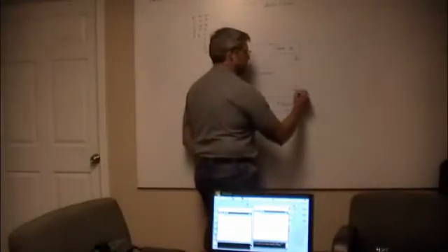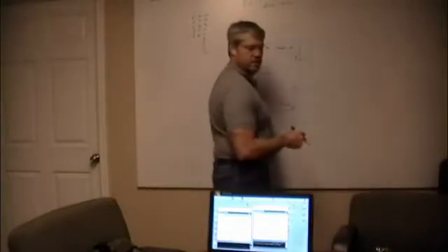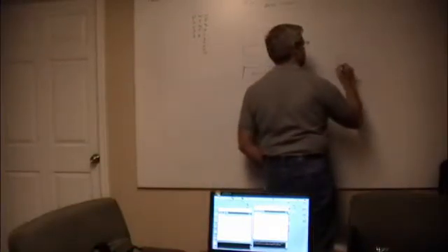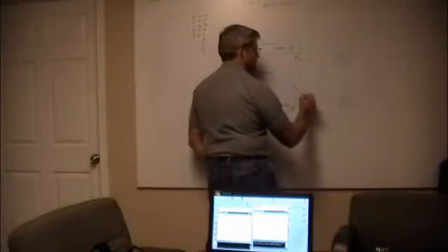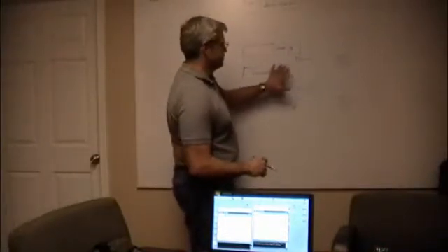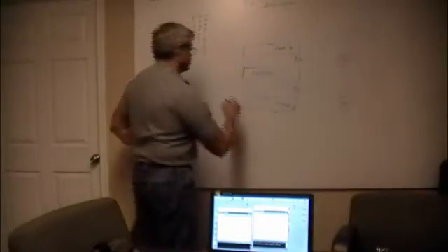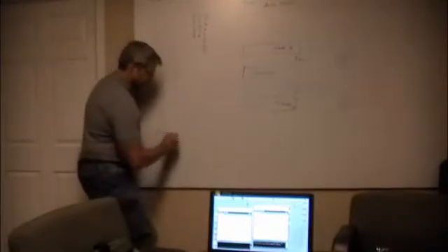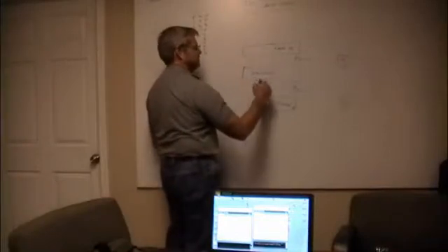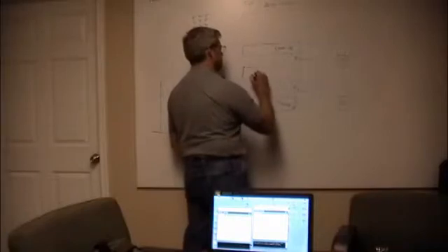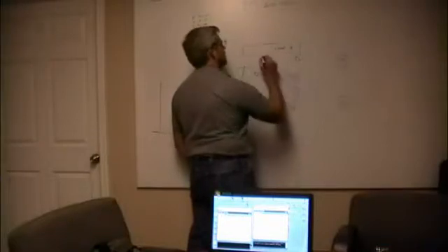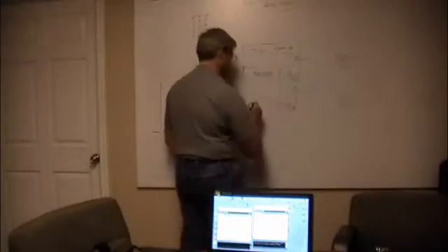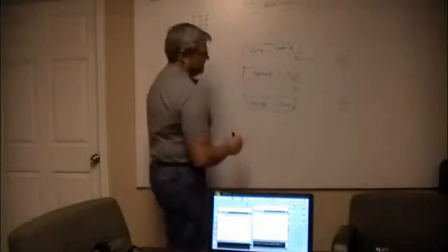There's a couple of control registers that you set up back here, but you've got 9 and 10, I think. So let's choose pin 9 and let's choose pin 10. The control registers can tell what the outputs of these things are, to control these pins directly. We talked about this before. If that's 9 and 10, then this must be, it's not a counter, it's a timer is what they call it. This would be timer 1, which is 16 bits, I think, and this would be OC1A and OC1B. And I think B connects to 10.